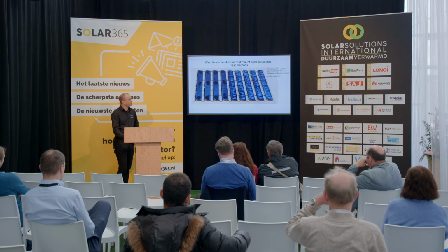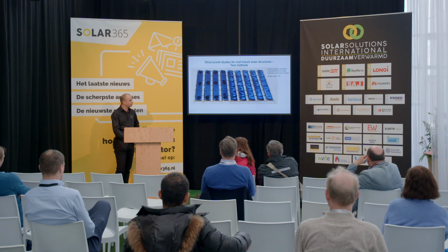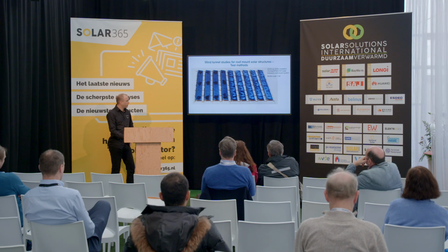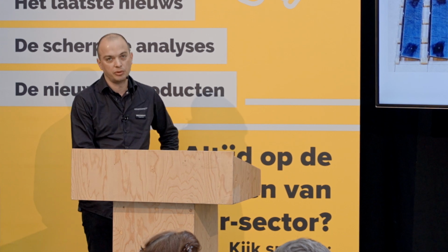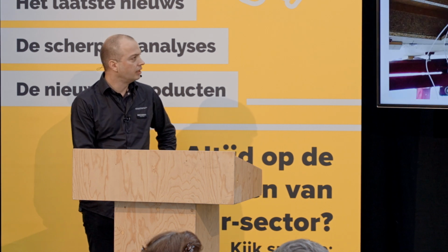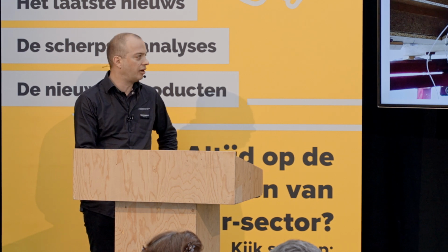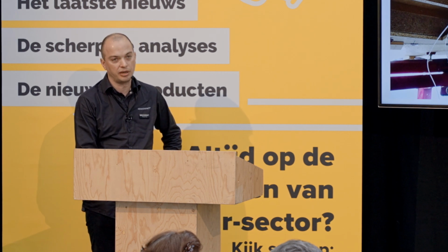So here's a close-up of a modeled array at a scale of 1/50. One can see some pressure taps on the top surface. There are also pressure taps beneath, on the underside, which cannot be seen. Here we have 9 rows, 5 are fitted with pressure taps, and the others are dummies, and both portions of the array can be exchanged against one another in the testing. There is, of course, the pressure tubing underneath the wind tunnel test section. We don't have time to dive into this deeper, but here we have a total of 250 pressure tubes.